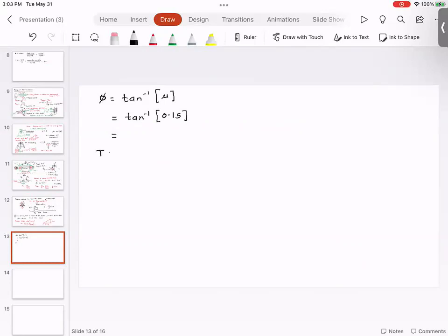So torque is equal to P multiplied by dm by 2 tan of phi plus alpha. P is 30 kilonewtons. 30 divided by 2 multiplied by tan of phi plus alpha. Let me see how much is the value.